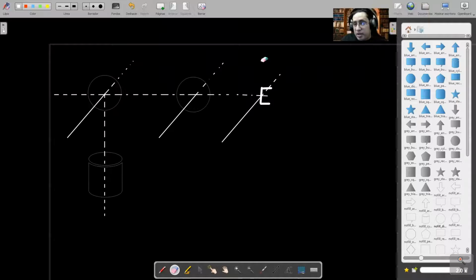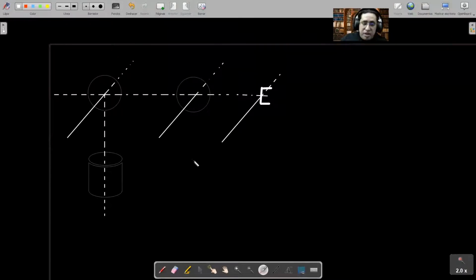Been drawing here, we have a rotation around this axis. We are rotating here. This is denoted by this joint. We can start numerating the joints. We know this is 0, 1, 2. And here we have the end effector, and of course, we go from 0 to n-1 because we have n equal to 3. This is the number of degrees of freedom we have.